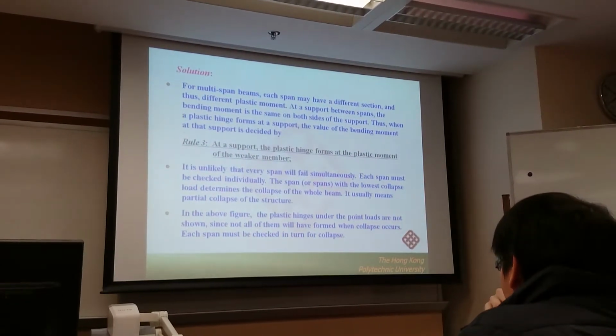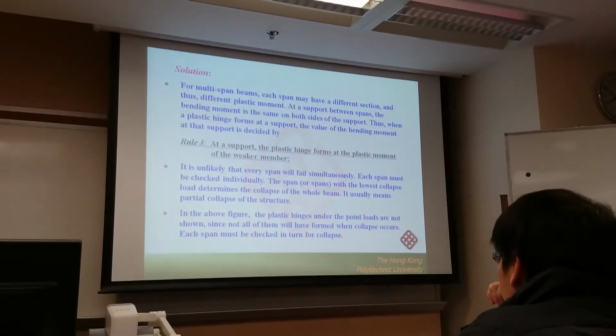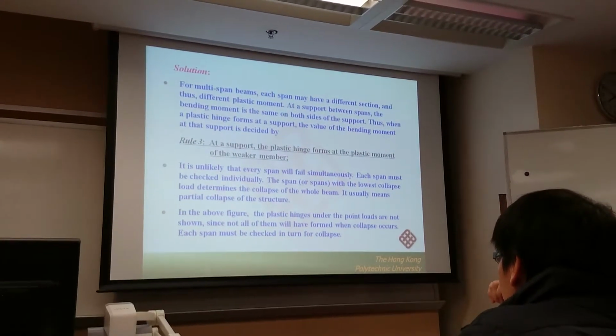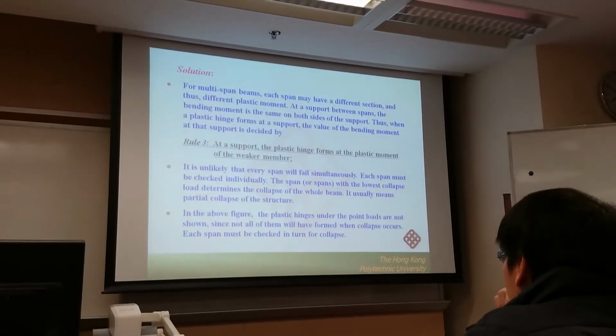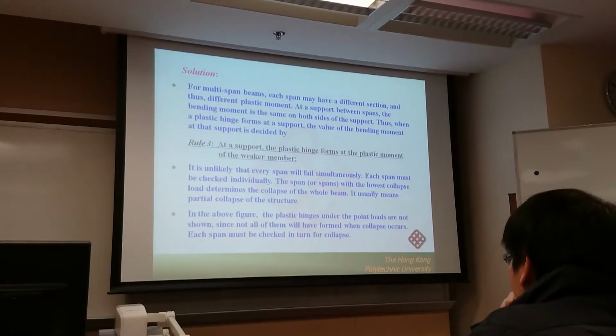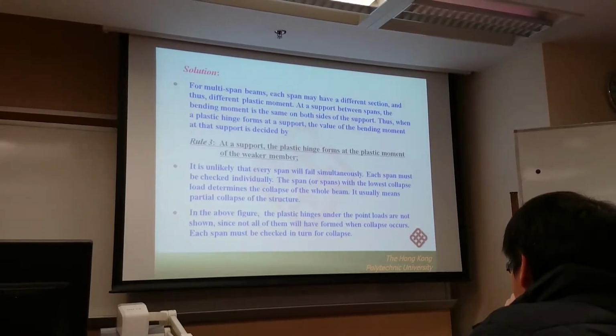When rotation is allowed, the continuity is destroyed. So you just need to analyze span by span, and the collapse is a partial collapse.